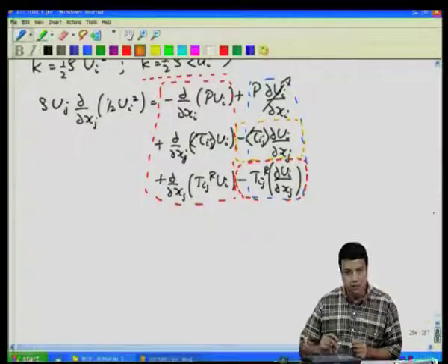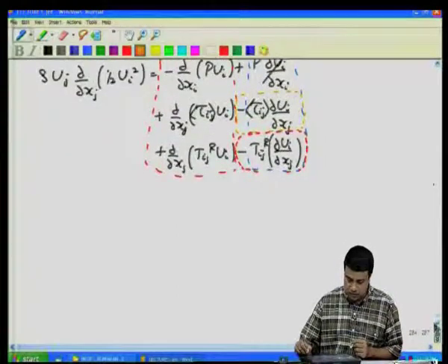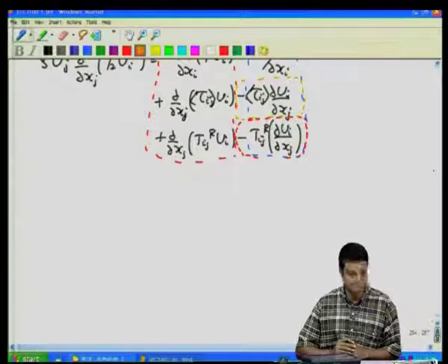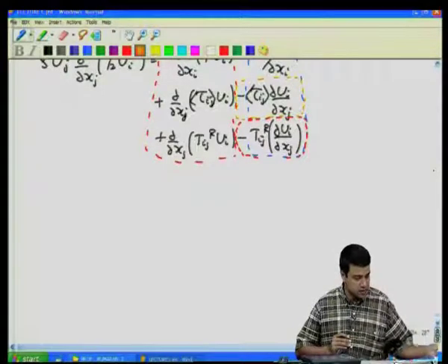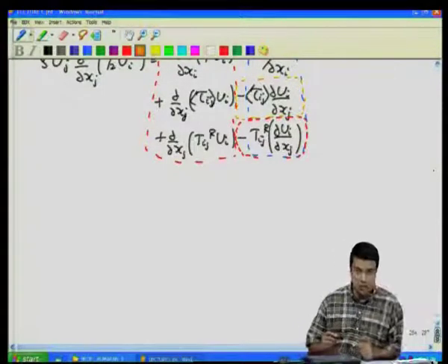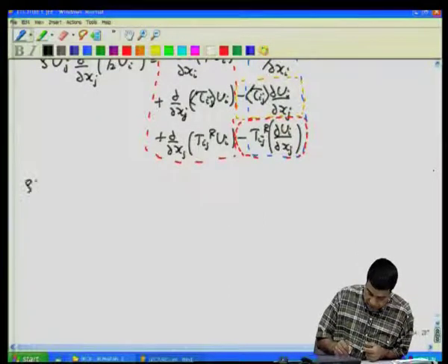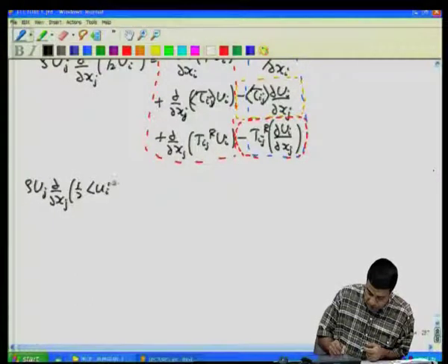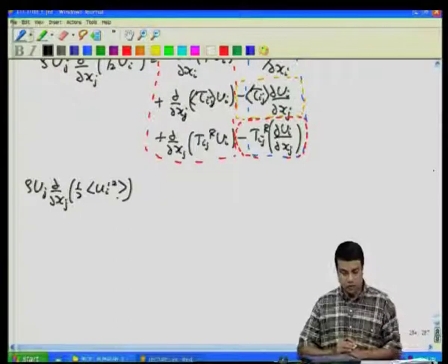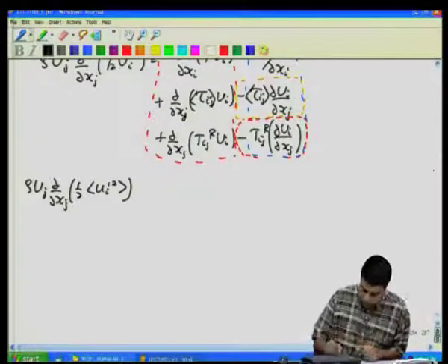So, where does that energy go? In order to see that, one has to write a conservation equation for the kinetic energy of the fluctuations. I did not go through the details of the calculation in the last lecture, but just wrote down the final equation. It becomes rho uj partial by partial xj of half ui prime square. The fluctuating velocity is equal to